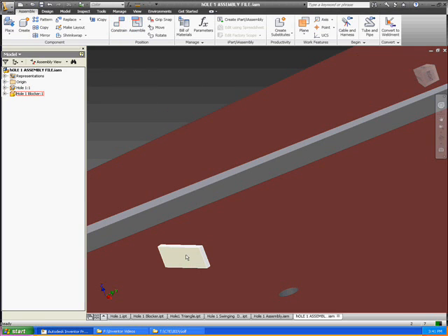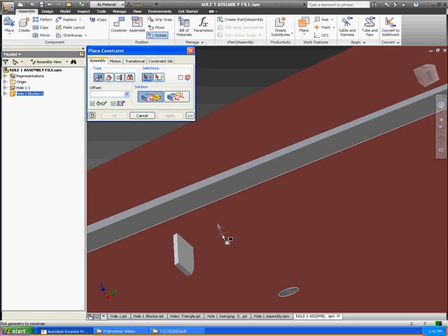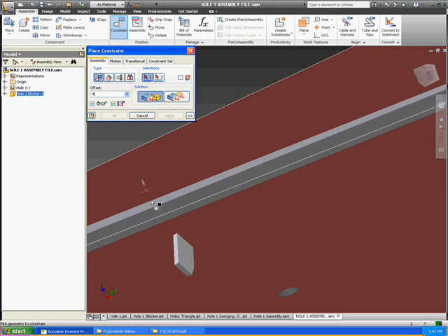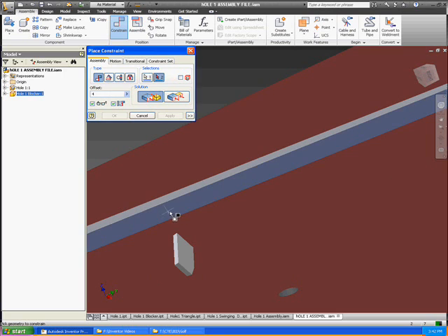Next, you want to rotate the component into position, and the constraint that I'll apply is between this face and the face of the blocker that is actually in line with this face, and that will allow me then to animate that mate constraint to move the blocker back and forth. So I start by turning on the constraint. I'm going to leave it at mate. I'll set the offset to 4 inches so it's not right up against the wall, and I click that wall to get started.